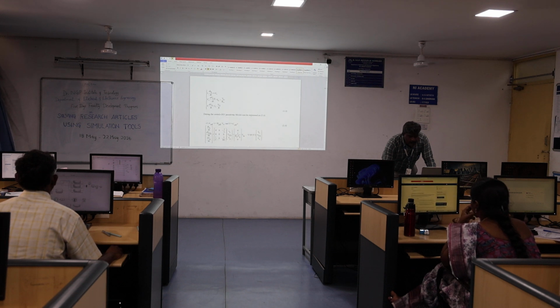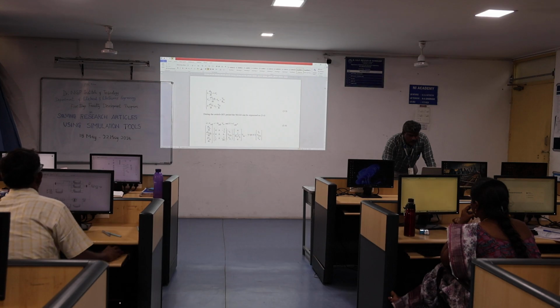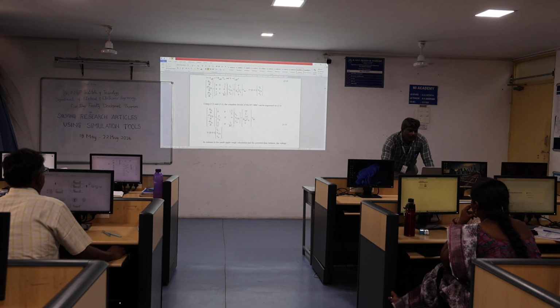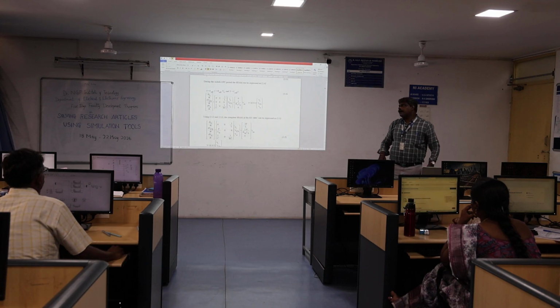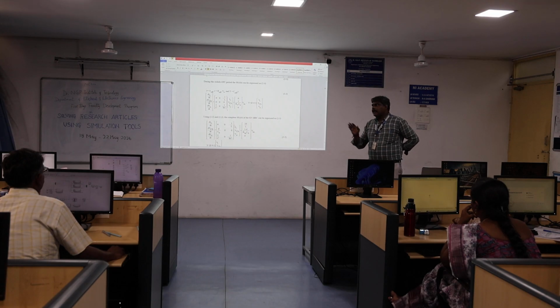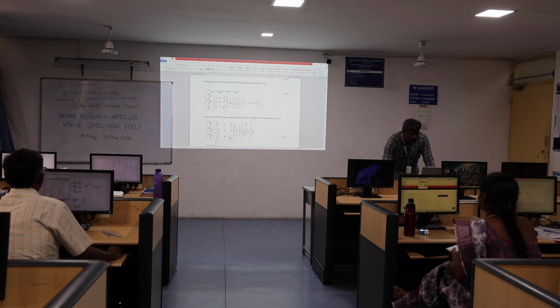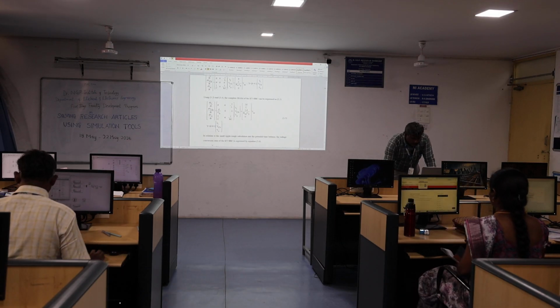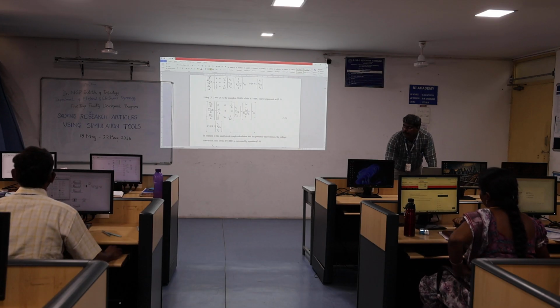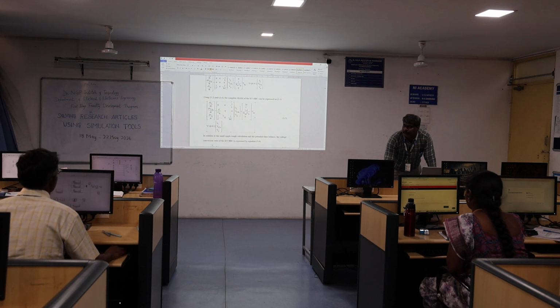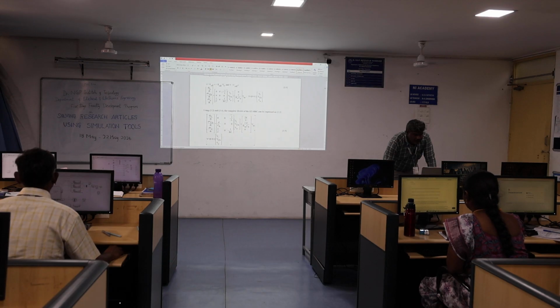Next, off time. In the same manner we form the matrix during the switch off time period. Then you can take the average. So the A matrix is equal to A on into duty cycle plus A off into 1 minus D. If you combine these two, you will get the complete A matrix. So A on into duty cycle plus A off into 1 minus D, where 1 minus D is the off time period, 1 minus D into the switching time period. So 1 minus D into A off; this is the A off matrix.